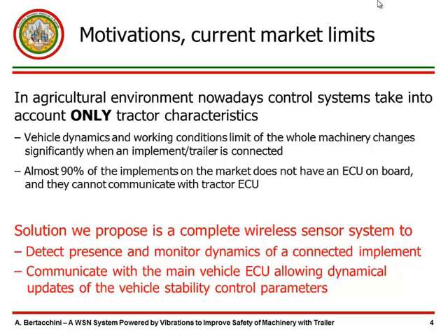Moreover, almost 90% of the implements on the market have no ECU on board, and consequently they cannot communicate with the tractor ECU. For this reason, we propose a complete wireless solution, able to detect the presence and to monitor the dynamics of a connected implement, and able also to communicate with the main vehicle ECU, allowing dynamical updates of the vehicle stability control parameters.